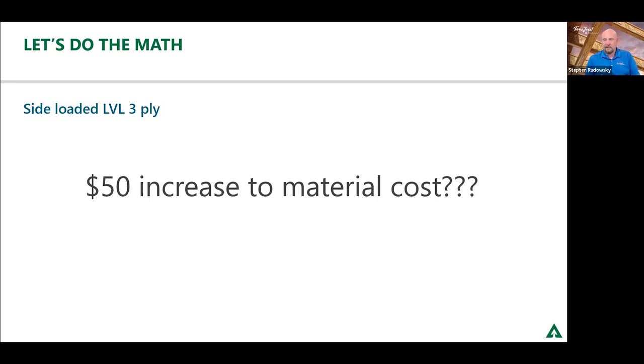So I've got a question on here from Jeff Kelly. He said something about, do we offer flitch beam buildup? Man, I wish we did. Unfortunately, we have not gotten to that point yet. And the easy answer is wood and steel act differently, so it's very difficult to teach a computer program to do that. A lot of people still do hand calcs when it comes to flitch beams.